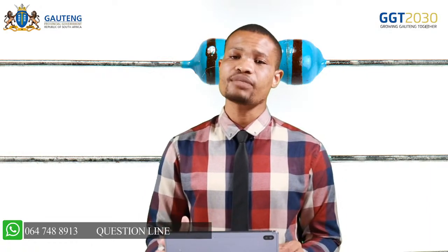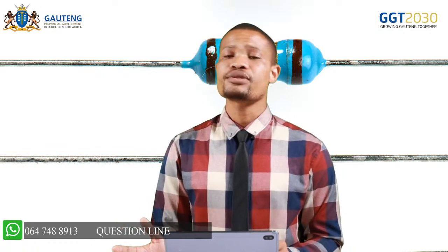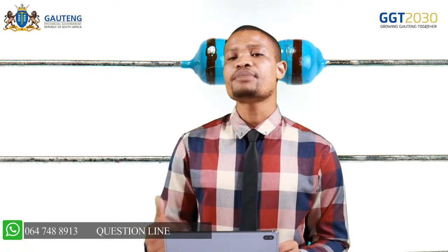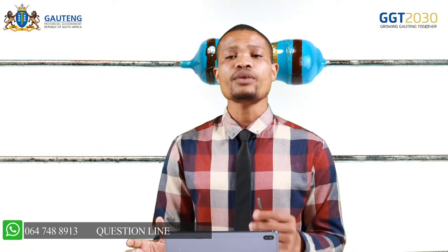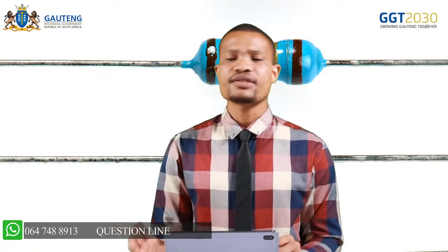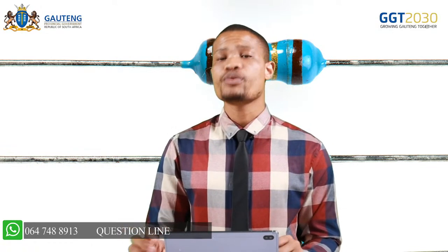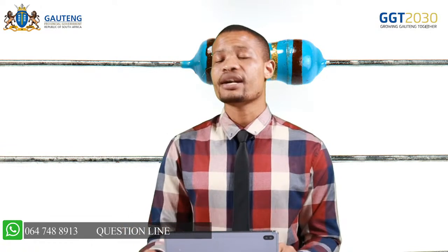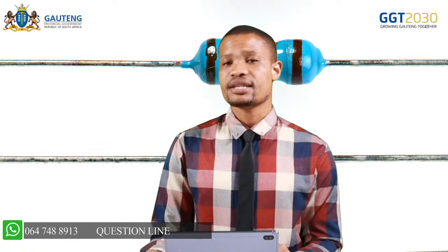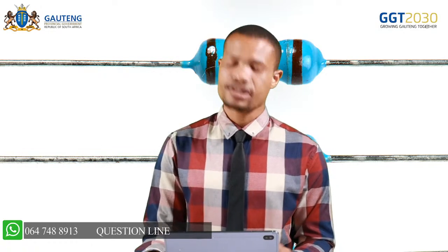We will be using a circuit board to demonstrate and take measurements, looking at how to use a voltmeter, how to use an ammeter, and how to connect the ammeter and the voltmeter. The voltmeter is usually connected in parallel, whereas the ammeter is connected in series. The reason for that is very simple. It is because the voltmeter has a very high resistance. If we were to connect it in series, there would be no current flowing. But an ammeter has a negligible resistance, so it works to connect it in series because its resistance will be negligible.